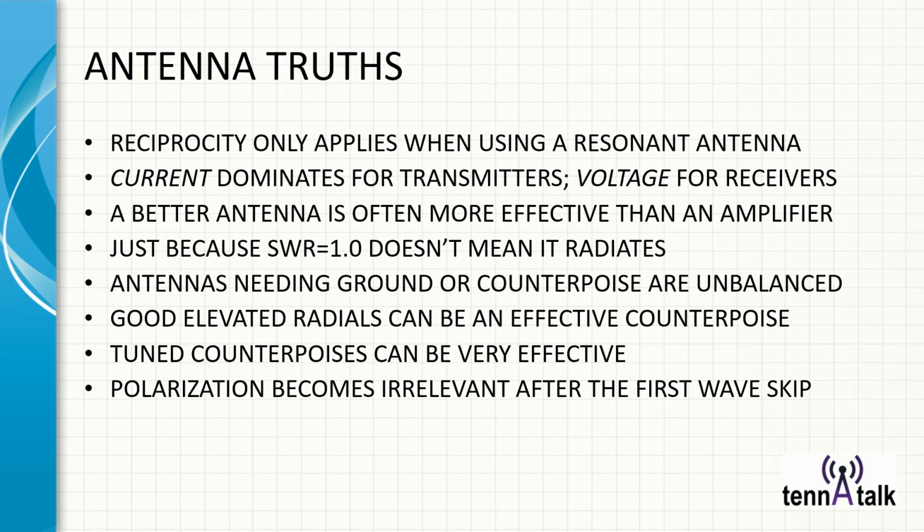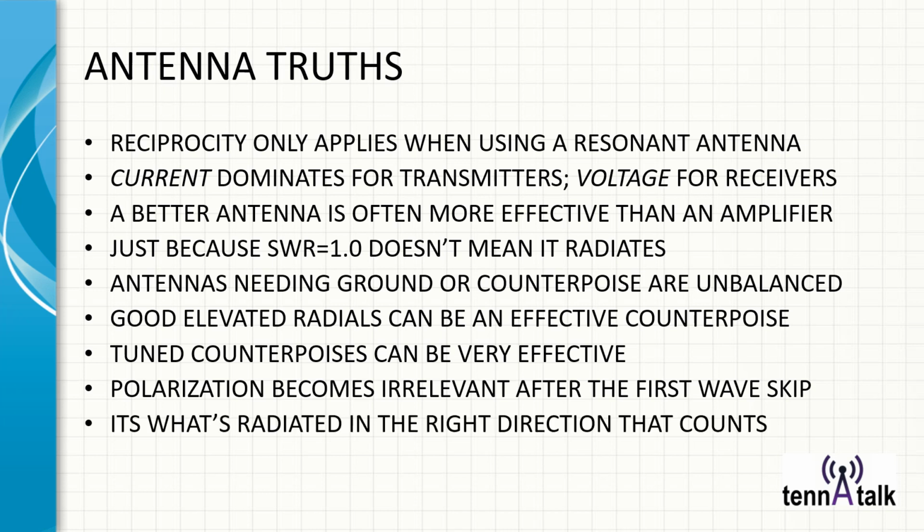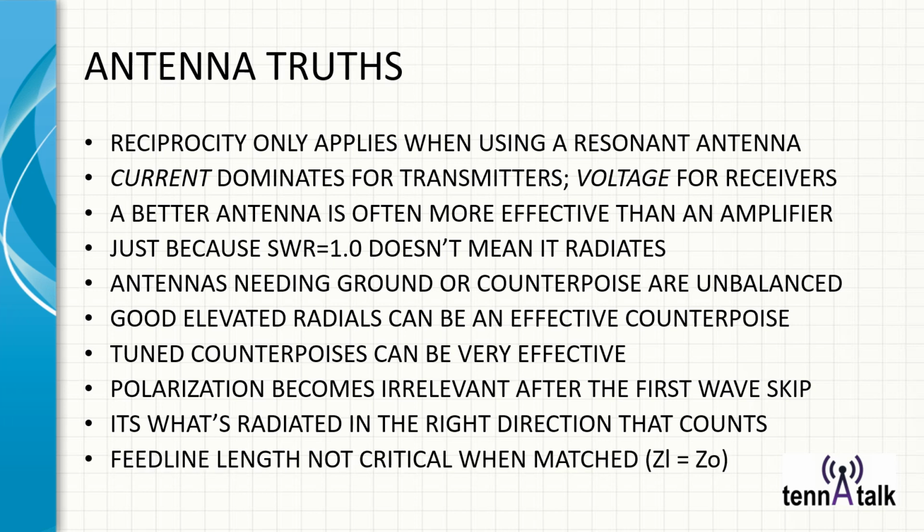Polarization becomes irrelevant after the first skip. So unless you're doing point-to-point, I wouldn't worry about polarization. And it's what's radiated in the right direction that counts at the end of the day. Feed line length is not critical when its impedances are matched, the load to the feed line. So we talked about that before.